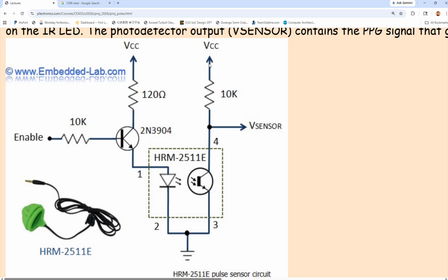If you have a little amount of current flowing through this resistor, there will be a drop, right? So this will show a voltage around, I don't know, but it shouldn't be 0, shouldn't be 5. It should be something in the middle. Okay? And then you start having more photons being received by the receiver or less, and that will be the signal swing around that static level, right?